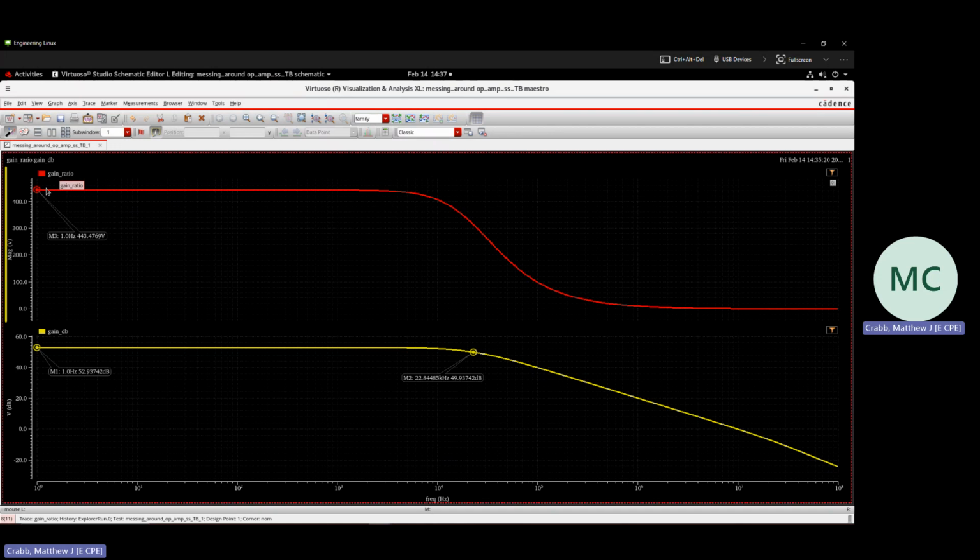And so I can do this, and then I could also find at 1 hertz up here my gain and my ratio gain. And I can take this like 443, multiply it by 22.845 kilohertz, and that'll give me my gain bandwidth. Okay, so that's the way you can do this graphically, and you can use these nice graphs for your lab report.